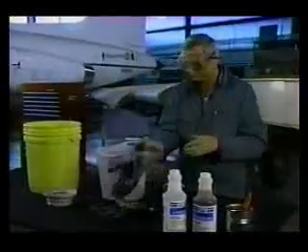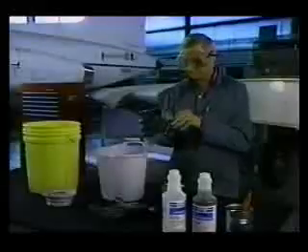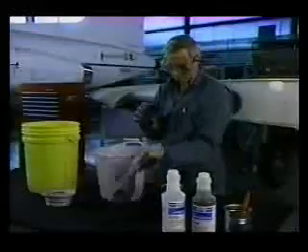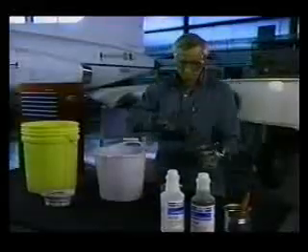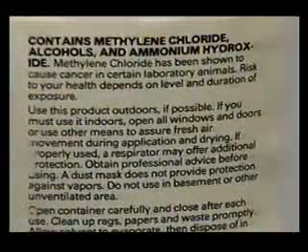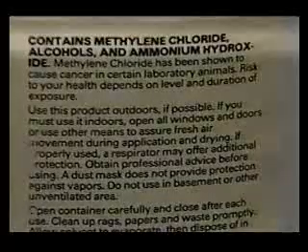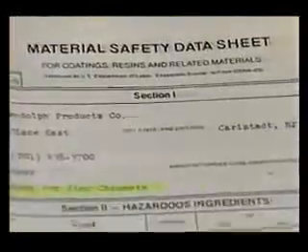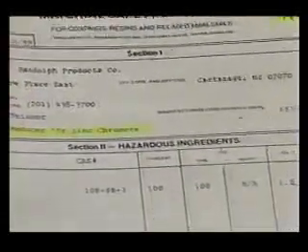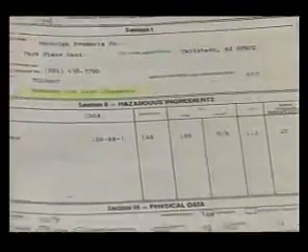Do not use chemicals of any sort in small, unventilated areas, and always wear a respirator when directed by the manufacturer's instructions. Do not use paint removers containing acid on aircraft surfaces. Instead, use phenolic and non-phenolic paint removers. You should be aware that there are numerous environmental laws and regulations which may restrict the use of these products. Check to see if there are any EPA requirements which apply to your location, and be sure to follow all safety precautions.